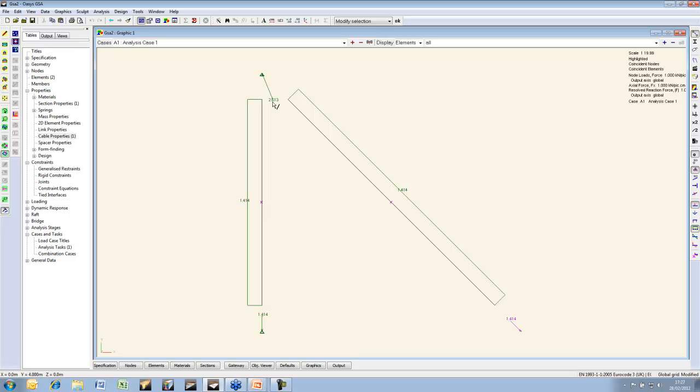So if you want to model a crane lift or something of that order, then they are very good for that. If you want to model a suspension bridge, the catenary shape, then they can be very useful for that too. But use with caution, because the end deflected shape might not be quite what you expect.